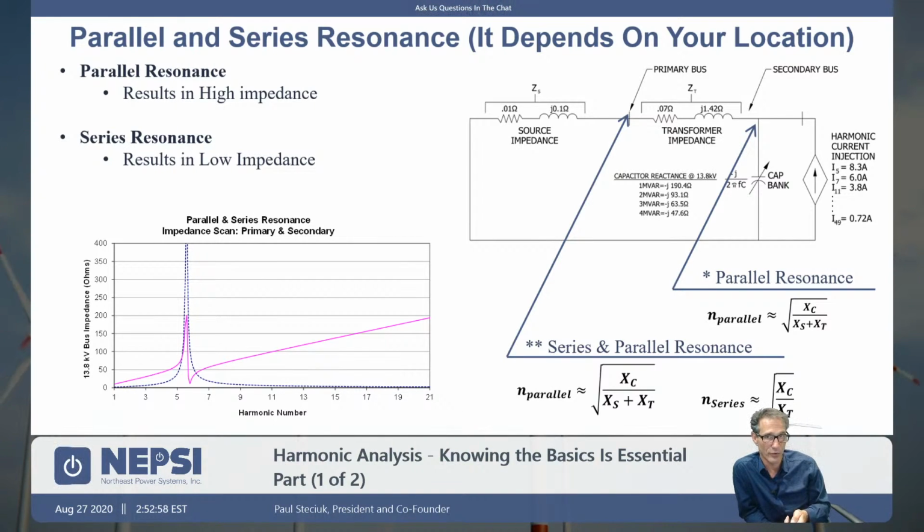For the most part, most companies are modeling that source impedance as a reactance. If there's a capacitor bank there, you of course have to ask, is that capacitor bank on the transmission grid side going to have an impact on the source impedance? And if it does, then you have to model it. So normally I do a sensitivity analysis. I ask the question on the transmission side, do you have capacitors there or not? What does the transmission system look like? Does it make sense for me to model back to the next substation to capture that impedance?